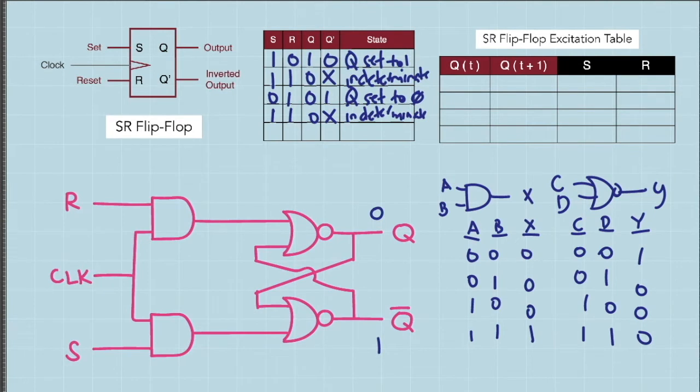For the final case, we will retain these previous values of outputs where Q is 0 and Q bar is 1. What if we supply the set signal and reset signal with a simultaneous value of logic 0? And at this instance, there is a clock pulse, which means that these inputs are both in logic 1.